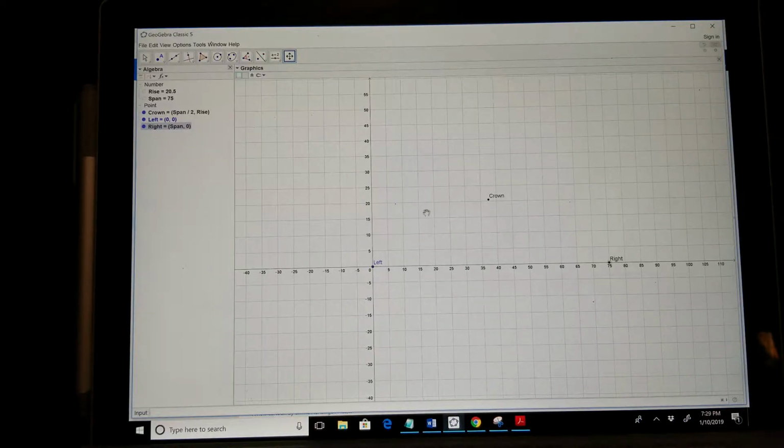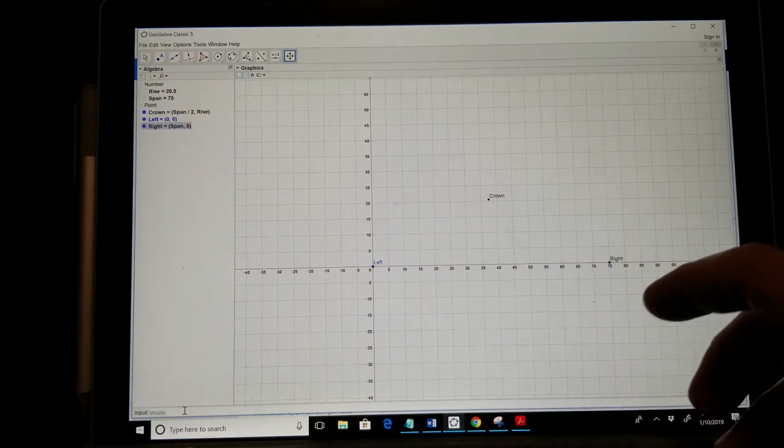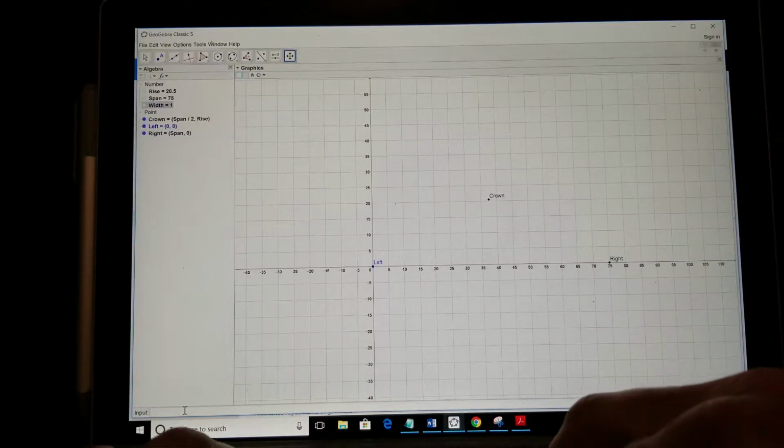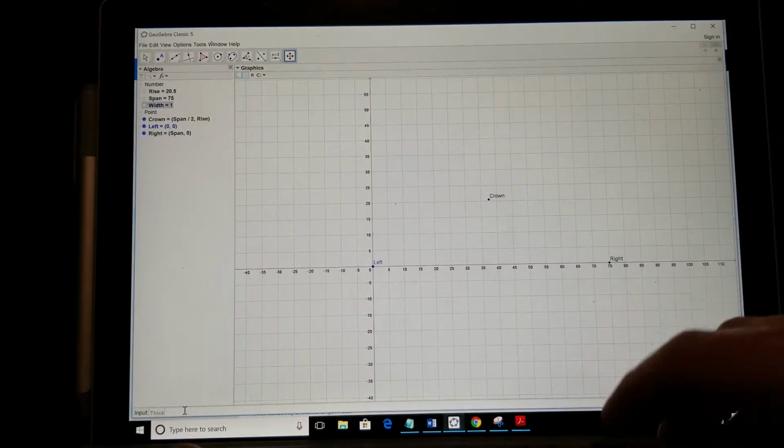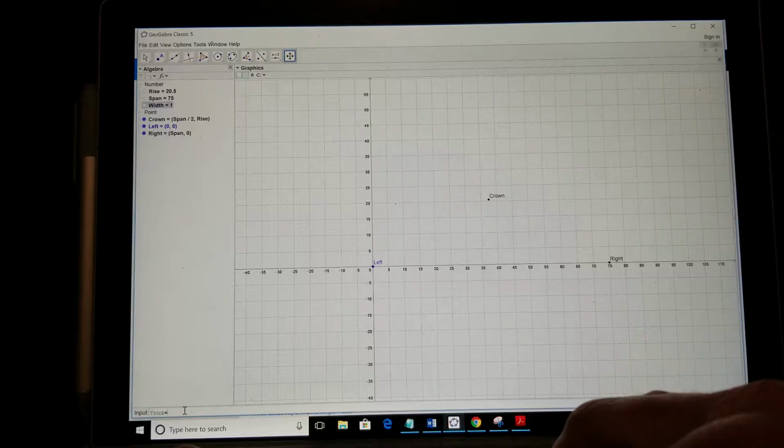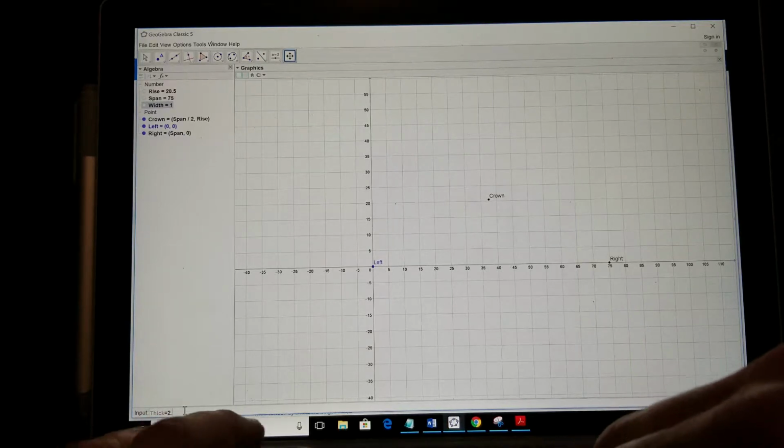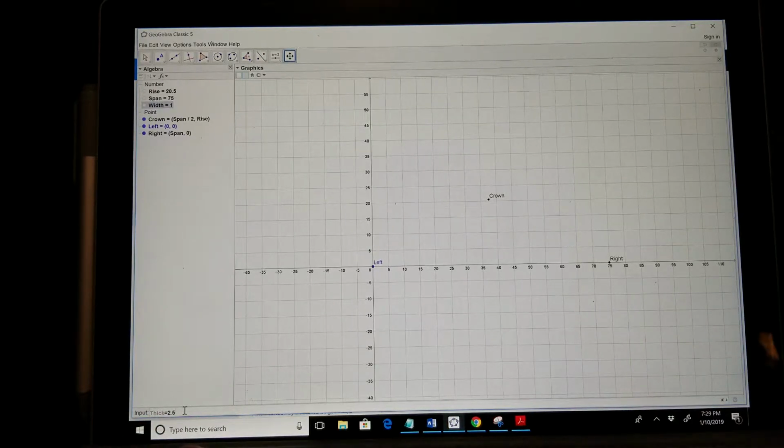And now I want to calculate the weight of this segment. It's a 1 foot wide segment. So I'm going to say width is 1. That'll be feet. The thickness of the shell, the thick, is going to be, let's say it's 2 or 3 inches. I'm going to say 2.5 inches. But GeoGebra doesn't recognize units, so we're just going to have to make sure that that's feet.